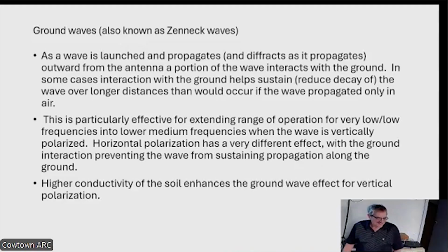So John, if I'm understanding what you just said, at the lower frequencies, ground waves exist only because of this relationship with the vertical antenna, vertically polarized signal wave, and conduction in the ground. So basically that means that there is no ground wave if I'm horizontally polarized. It's pretty weak, right? The horizontal polarization because of that effect. So at what frequencies, if I'm vertically polarized, at about what frequency does ground wave go away?